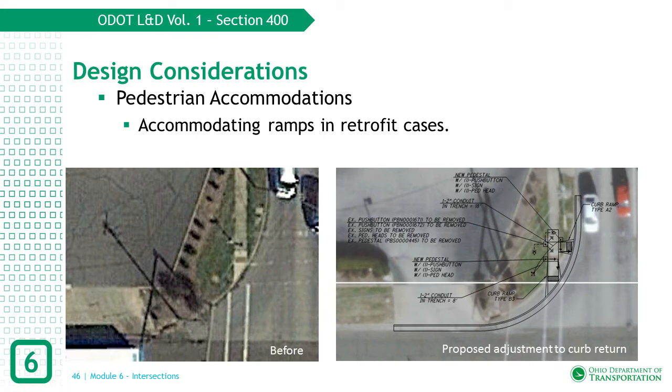Another example could be locations where existing site constraints do not permit the straightforward construction of a single ramp type. For instance, steep roadway grades can make a perpendicular ramp difficult to design and meet ADA requirements. Using a combination of a parallel ramp and perpendicular ramp to manipulate the slopes and achieve compliant grading may be necessary. Similarly, projects with curb ramp retrofits and minimal pavement reconstruction could require a small amount of full-depth pavement reconstruction adjacent to the curb ramp to ensure ADA-compliant grades can be achieved.